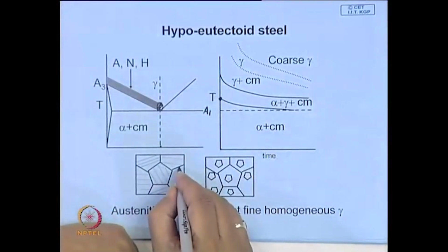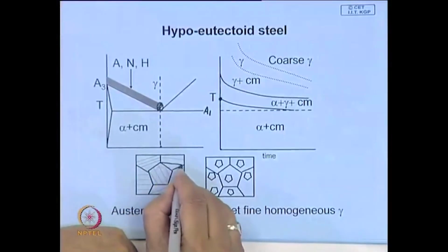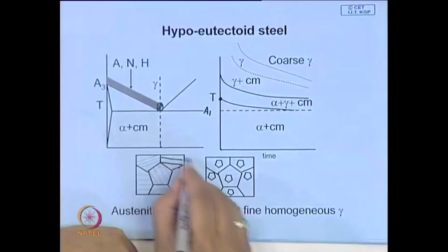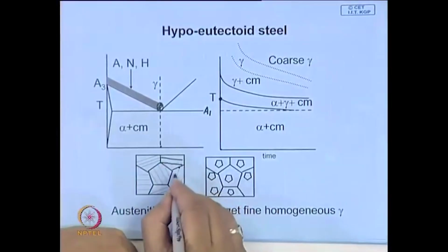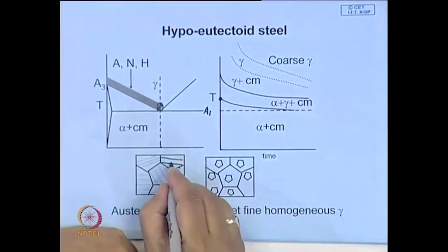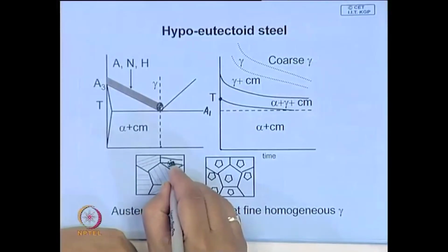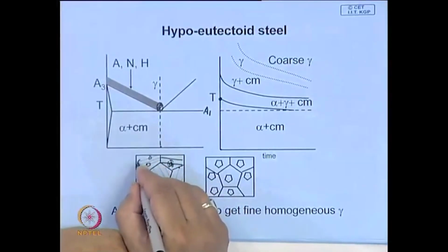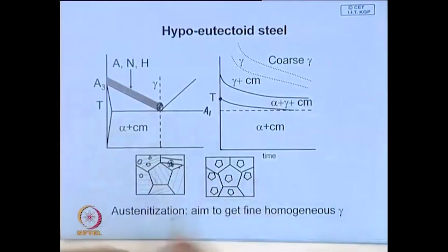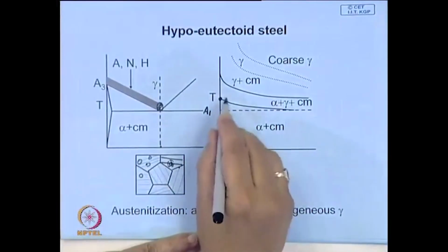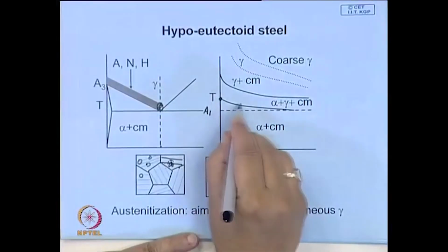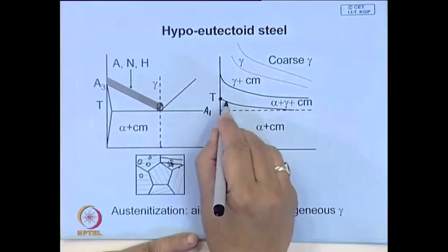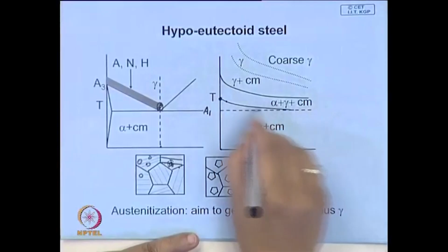What will happen is, if you have a pearlite made up of, let us say, these cementite plates in a ferritic matrix, then certainly a nucleus of austenite will develop over here, and this will try and grow. Similarly, this will develop at several places, and they will try to grow, something like this. So, this is time dependent. For a certain period of time you have to allow, maybe this is the time where this transformation starts.